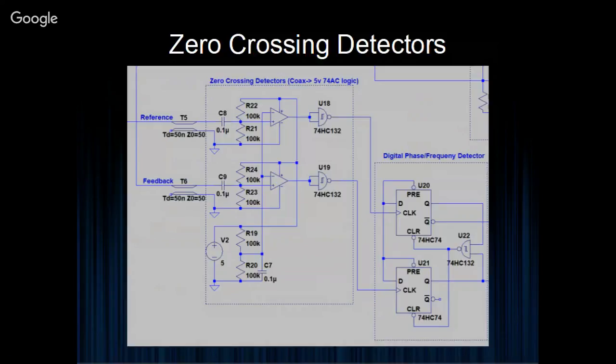Now, if you would like to lock the oscillator to the carrier frequency, you need a way of doing that. That's effectively a phase lock loop. Not just a phase lock loop, but a phase frequency lock loop. And the frequency lock is, of course, secondary to having a phase lock. If you've got phase lock, then presumably you've got frequency lock too. It's just being pedantic.